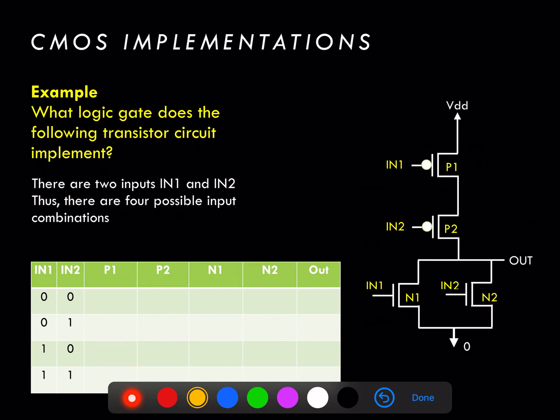Looking at yet another logic gate implemented in CMOS, we can follow the same analysis to figure out what this particular circuit does. When N1 and N2 are both equal to 0, the PMOS transistors both turn on and are modeled as short circuits, and the 2 NMOS transistors act as open circuits.